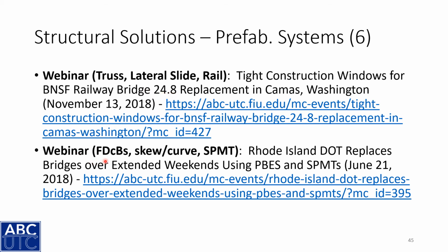And here is a concrete deck with steel beam superstructure. And this superstructure had a large skew and also curved beams. So SPMTs can be used even with skewed or curved beams.